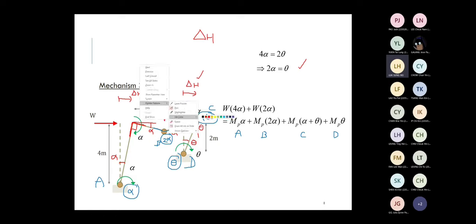About external work is equal to force times displacement. Unfortunately, this time you can see that you have horizontal displacement and you have vertical displacement. So you have to consider both works, both forces. Delta W, horizontal force times delta H, give you the first work done. Vertical force times delta, I call it delta V, V for vertical, okay, H for horizontal. Vertical force times vertical displacement give you the second work done.